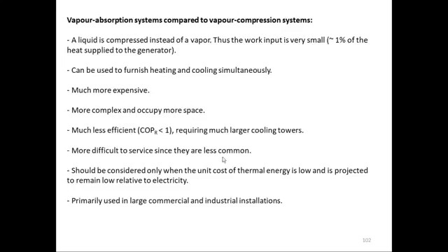Should be considered only when the unit cost of the thermal energy is low and is projected to remain low relative to electricity. So this is only viable where you have waste heat energy available, either waste heat coming from a steam turbine or from a gas turbine, or if you have a solar system installed in your factory, then it is a viable thing. Or sometimes some industries are using steam, so waste steam is available, then you can use this system.